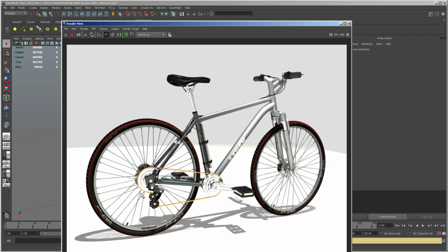So like I said, using techniques that we've discussed in this course about UV unwrapping and texturing, you should now be able to UV map, these are simple planar maps, and add some texture to all these gears, all the links, which will take a while. I suggest you select the whole chain and do a Z direction planar map of it, and then start breaking away the individual parts, the bits at the back, separated, and adding a bit of texture to them as well.